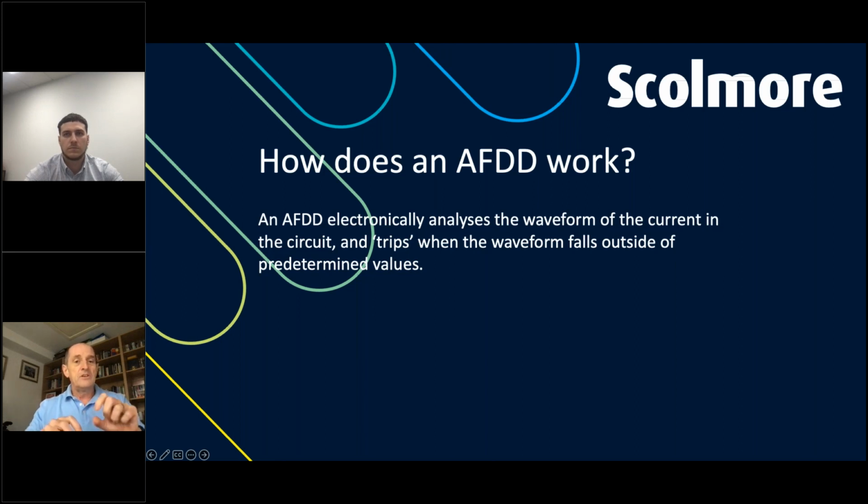It's that nuance where manufacturers are having to do the work to make sure that, yes, this is truly an arc. And so what they do is, rather than looking at one thing, as you rightly say, they look at multiple factors and go, actually, we need to have that and that and that. Only when all those appear do we say that this is an arc that we don't want. It's an unwanted arc that needs to operate a protective device.